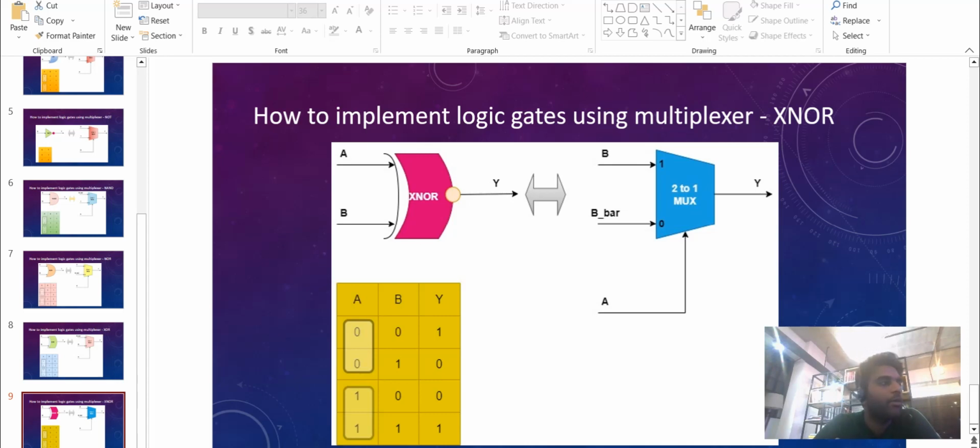Similarly, you can implement any complex circuits like adders, half adder, full adder circuits, and comparator circuits. So any complex circuit also can be implemented using a multiplexer. Multiplexer is a very important circuit in digital design. Let us practice with the multiplexer, and see what different circuits can be implemented, because this is a widely available resource. When there is a resource crunch, it will save a lot of space for the implementation. And as a design engineer, you should always look into alternative and better-performing implementations.